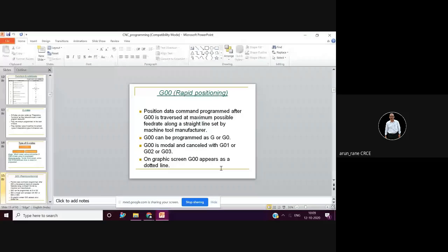So now this is how to read this. This is G00. So it is not GOO. G00 stands for rapid positioning. That is, the movement will happen in rapid. Rapid means at the rate of 10 meters per minute or 15 meters per minute. That is what we are talking about, rapid positioning. How to read it? G00. See, 0 means zero, and if it is O, then it is round. O is a round or a circle.